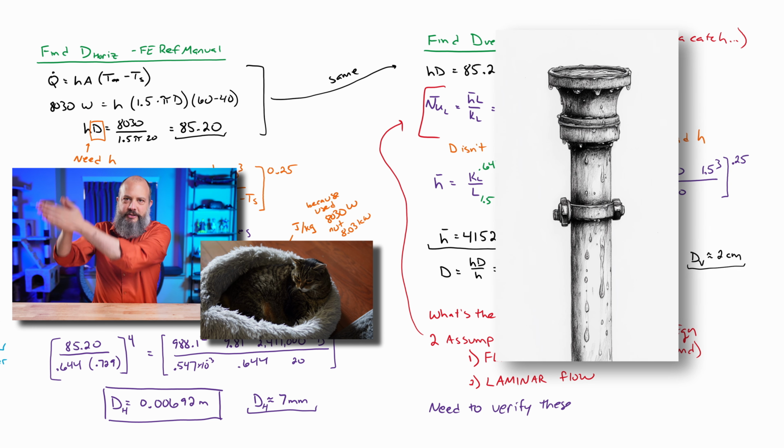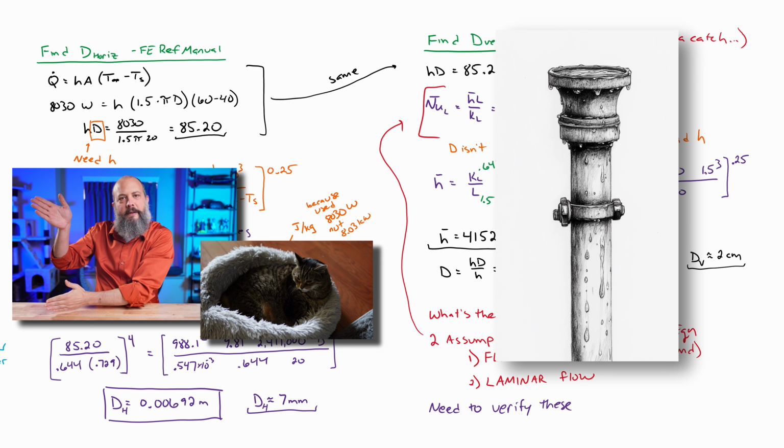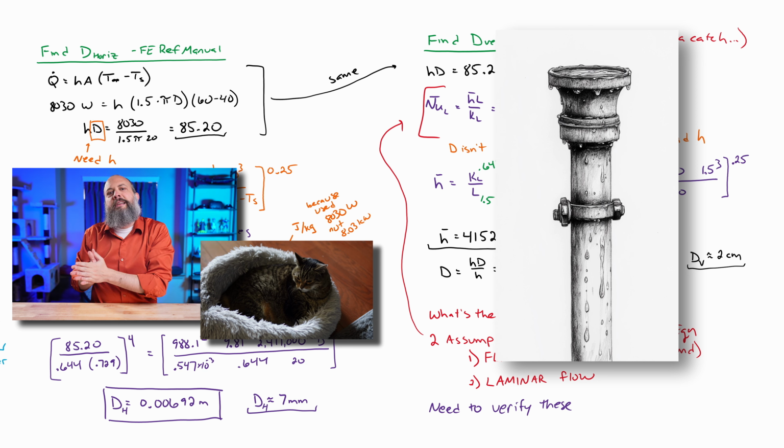But for a vertical surface, when you have water condense on the top, as it falls downwards, it's flowing along the surface of the pipe. All of the water that condenses along the surface is flowing down in a sheet of liquid, like in a film. If you just have a tiny amount of water, then the flow will be a very small amount of flow. It will be laminar flow.